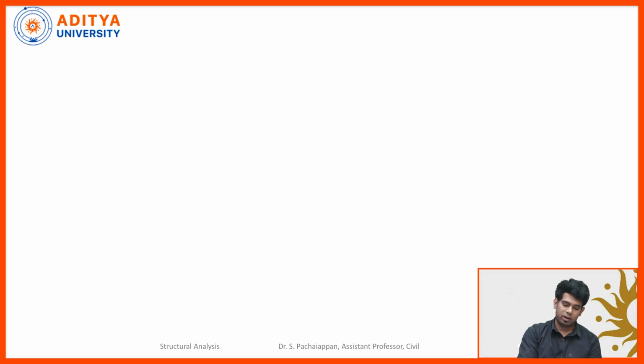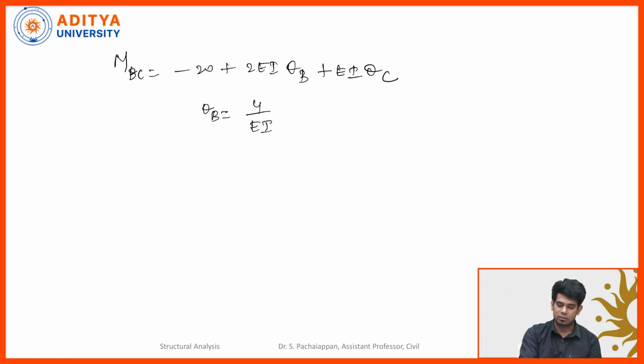Now we are going to write the value of MBC. So MBC equation already we have, which is minus 20 plus 2 times of EI into theta B plus EI into theta C. So what we are going to do here, theta B we are going to substitute 4 by EI, theta C we are going to substitute minus 12 by EI in this equation. Let's substitute.